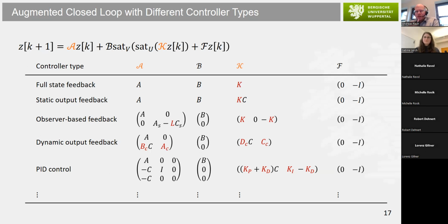Do you have an idea how to, let's say, switch between both types of controllers in a smooth manner? Could this be integrated? You mean something like gain scheduled control? Yes, I'm thinking in this direction, whether this would be some kind of gain scheduling, where you fade out the one controller and fade in your approach. The question in this part would be where to switch, because I think the controller that brings the pendulum upwards can only stop when it's really upwards in the end.